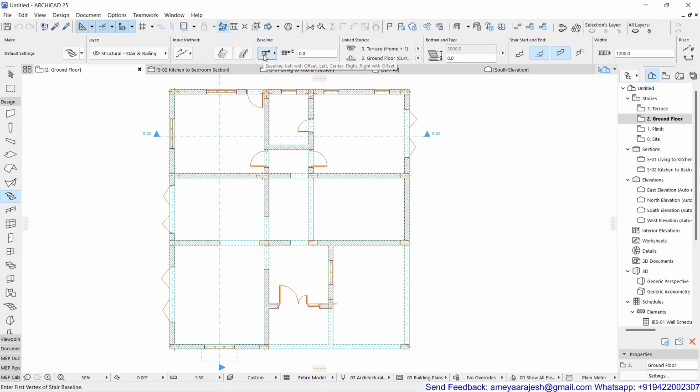This is just like a geometry method concept, because the way you used to place the wall, from the reference line, the overall wall thickness is either distributed on the left side of this reference line, or the right side, or center justified. So the same logic you can apply over here. Okay, so let's try to keep this, something, for example, okay, I'll just go for this for a while. Let's see how it goes. Don't worry, you can change it anytime at the time of drafting also.